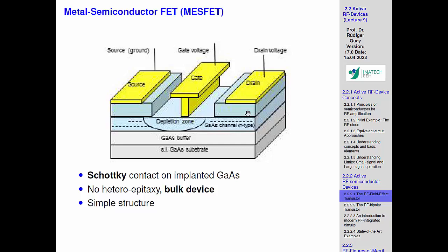And it was on a good substrate, that also helped a lot, because the gallium arsenide, which we have in the background here, the substrate itself, is particularly isolating. So this is a perfect waveguide. When you take the right gallium arsenide, it is a very low loss isolator. So it's a very nice substrate, but contrary to silicon, it's very low in conduction. So 10 to the 10 ohms or so. So really low. So that helped.